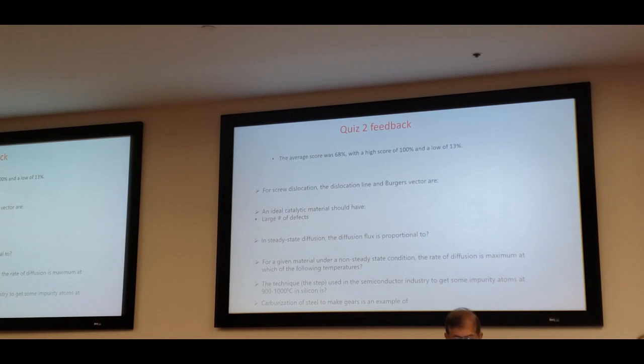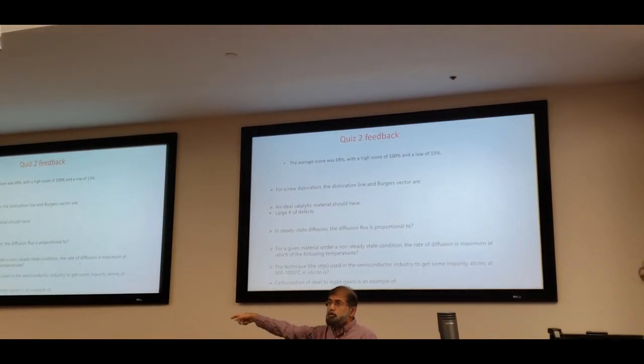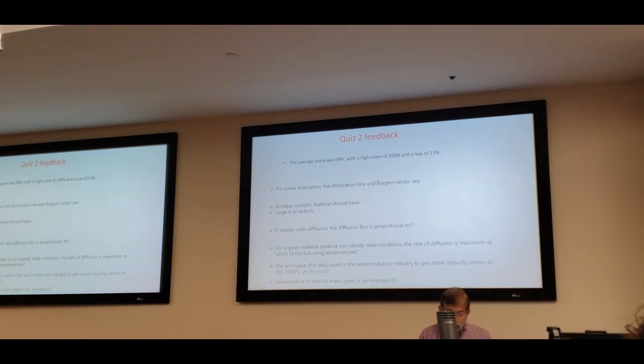Okay. So I remember I said that that's important, even for the next chapter. So remember, for the edge dislocation, it is perpendicular, right? You see one incomplete plane, it moves like this, so your dislocation line is perpendicular to that. Whereas for the screw dislocation, what is screw dislocation? This is the screw dislocation. That's the reason why it is parallel. We are going to learn more about it in the next chapter. So remember that. Any questions?